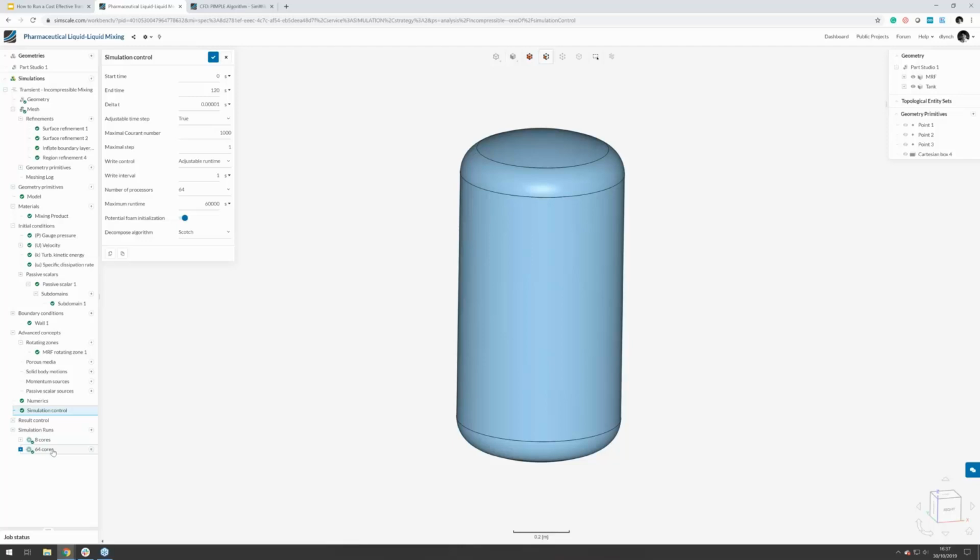So in this case, because we're dealing with a mesh that's so small, 230,000 cells is not a big mesh size. If we solve that on 64 cores, the very fact that we're splitting the domain up into 64 different pieces and sending them to different processors, and the fact that they have to all communicate with each other, is going to slow the simulation down. So when you think you're going to be getting the simulation back faster, what you're doing is actually throwing more money at it and getting it back a tiny bit faster. And you've got to be able to put a sensible number on these simulations.